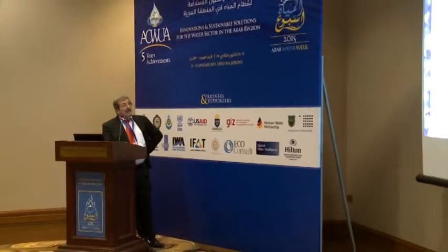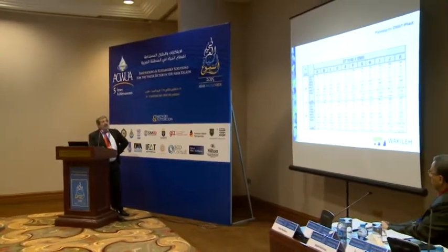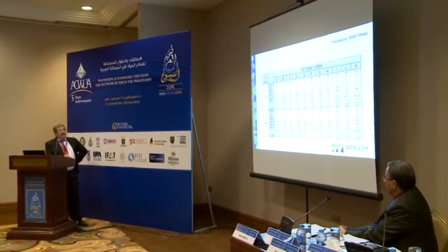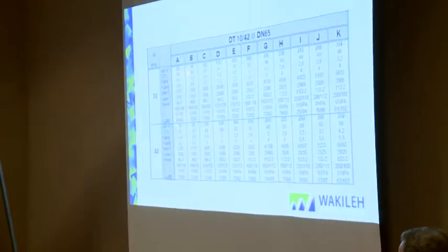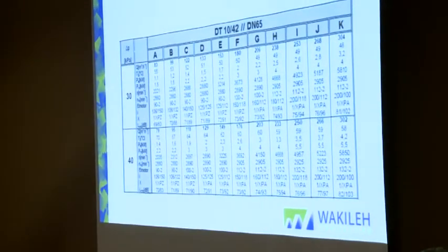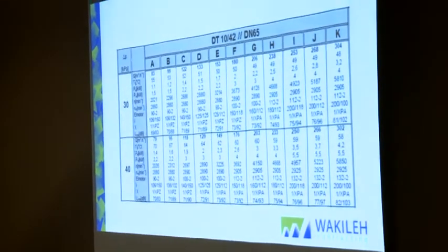The difference is very small. The power consumption or the motor required is little. Here it's 1.5, here it's 5.5, and that corresponds to a small part of the cost. But the blower itself is still the same blower. I can use this same blower for 3 plants, or if I need a blower to give me 300 cubic meter per day with low speed, then I need 3 blowers, but I still can use 1 blower. So that's important, again, at what speed I'm going to run.